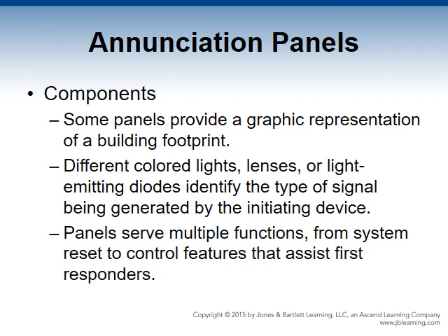Other panel features include system reset, alarm silence, alarm acknowledgement, alarm testing, and status indication for other systems. Access and critical system control features assist first responders. More sophisticated panels can further define the initiating device's location. The panel may also have system status indicators and control switches. These allow firefighters to start critical building equipment such as fire pumps, generators, stairway doors, or smoke control systems.